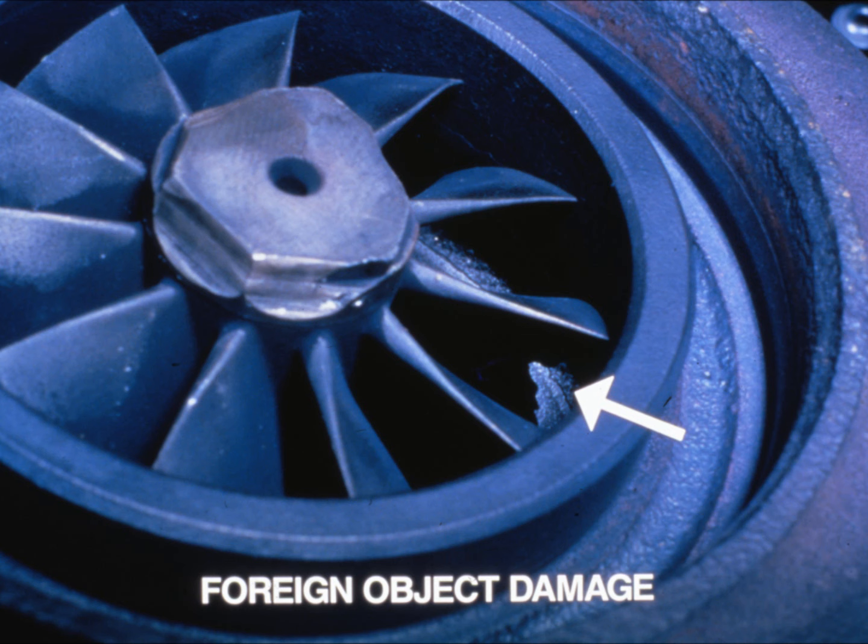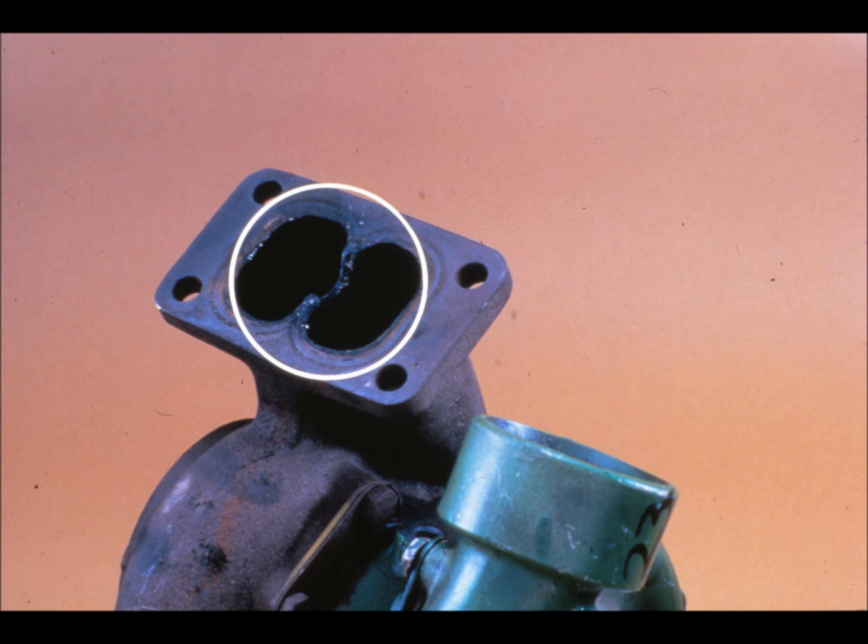Turbine wheel foreign object damage may also require an engine check. The foreign object must either be a nut, bolt, or other object left in the exhaust manifold or generated by an internal engine failure. The necessary repairs must be made. Excessive exhaust temperatures result from overfueling. The fuel injection system should be checked to be sure it is performing within specifications.